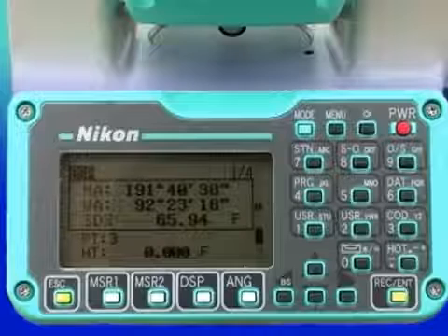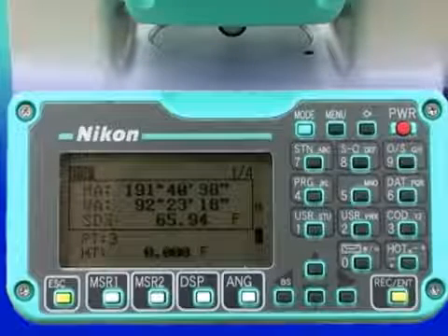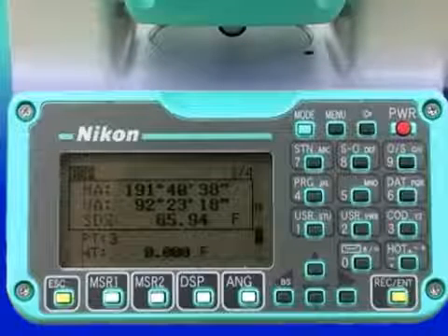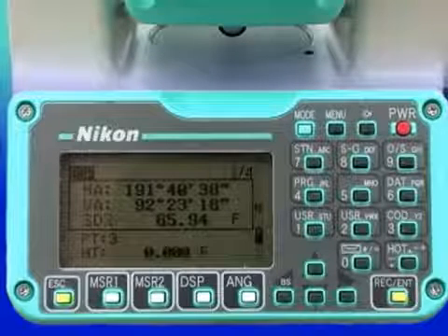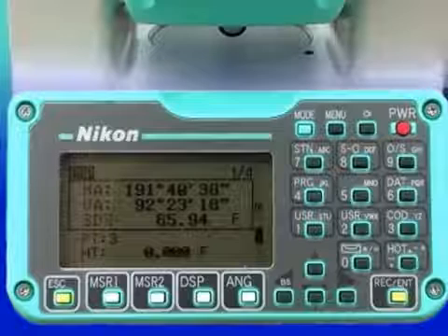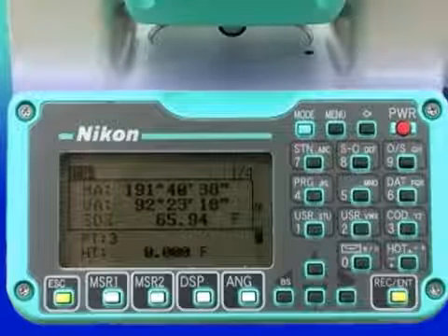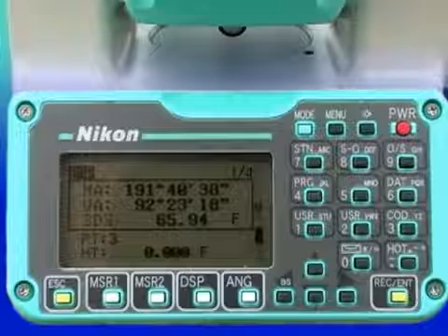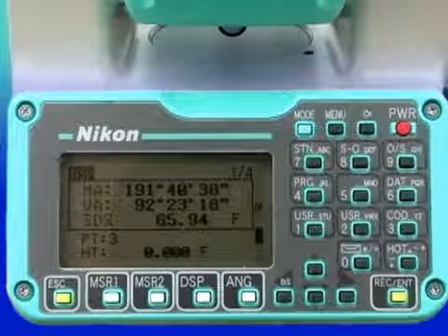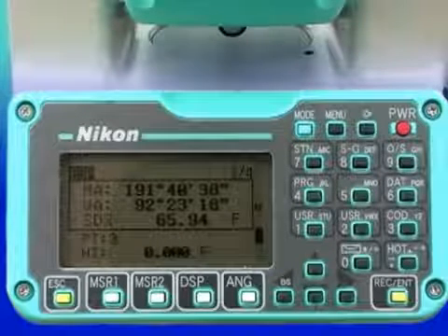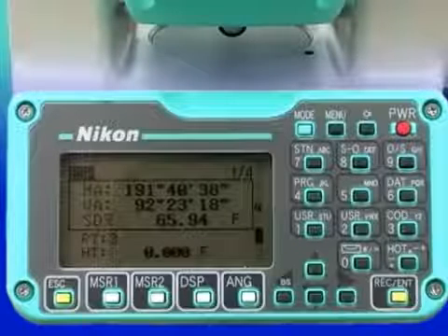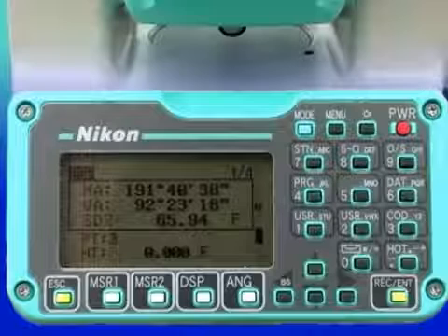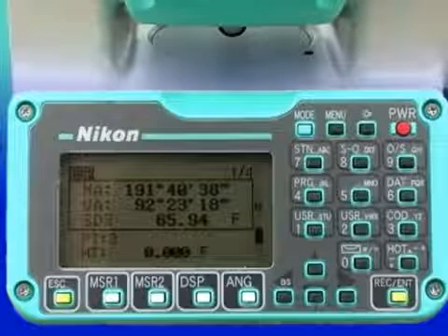Monitoring points while in the theodolite mode is done by sighting on a point to be monitored and recording manually the horizontal angle and the vertical angle. Several points can be monitored this way as long as the instrument is not moved. It is convenient to establish a reference point to set as the position of 0 horizontal angle. This is commonly referred to as the back sight, although the back sight is often located forward of the instrument.